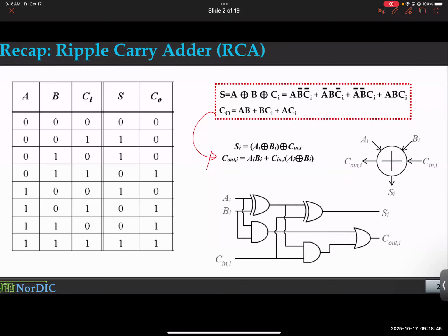It's not like, oh, there is another way to do sum and carry. That cannot be the argument. You have to achieve something by going through that approach. For this particular example, you can reuse some gates. Remember, reusing gates was a big deal for us. So you can reuse at least one XOR gate and so on. That is the biggest selling point.